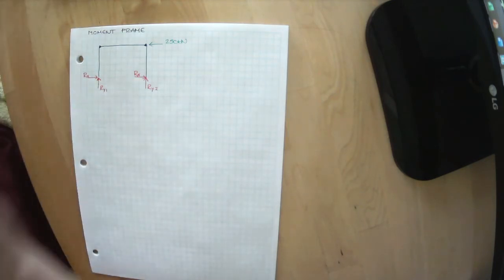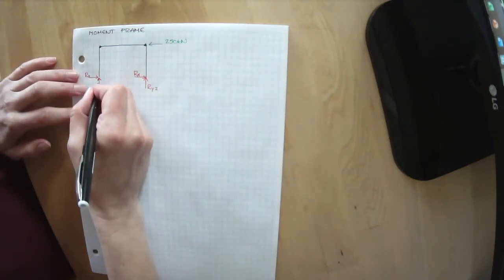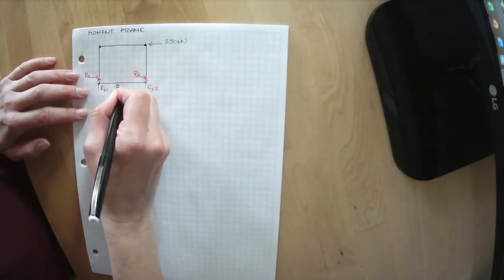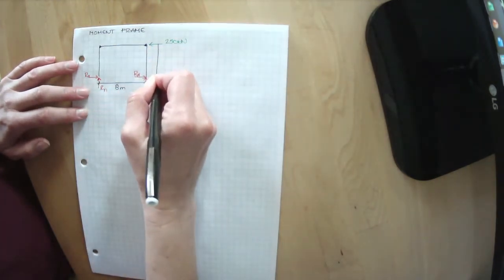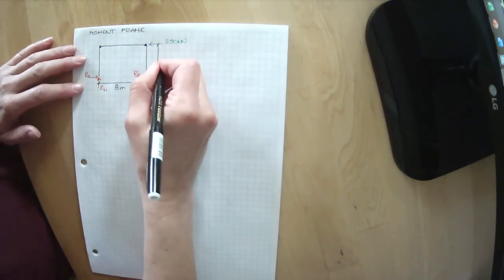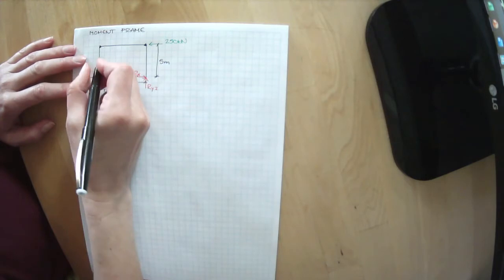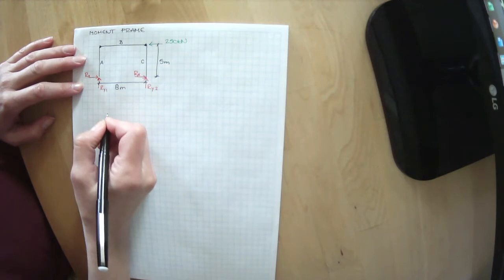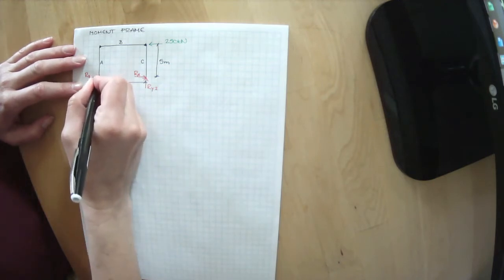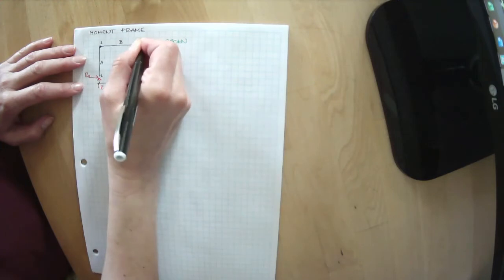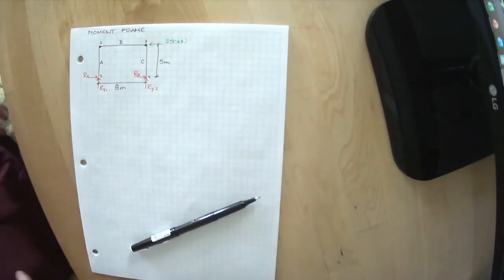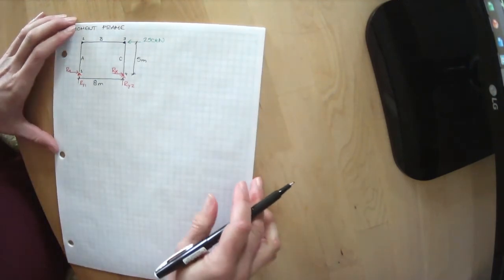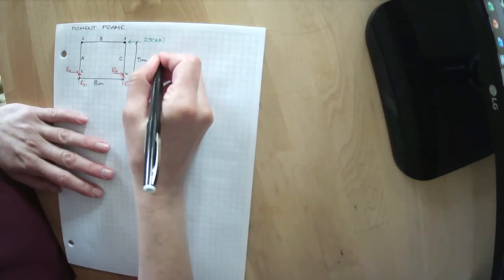And we know that when we do method of sections or trusses or anything like that, sometimes it's nice to label things. So where this has multiple planes, let's label things. Let's call this member A, let's call this member B, we'll call that member C, and let's label our nodes. We'll call that node 1, 2, 3, and 4, just because that might come in handy later while we're doing this. So first things first, let's solve for our reactions.